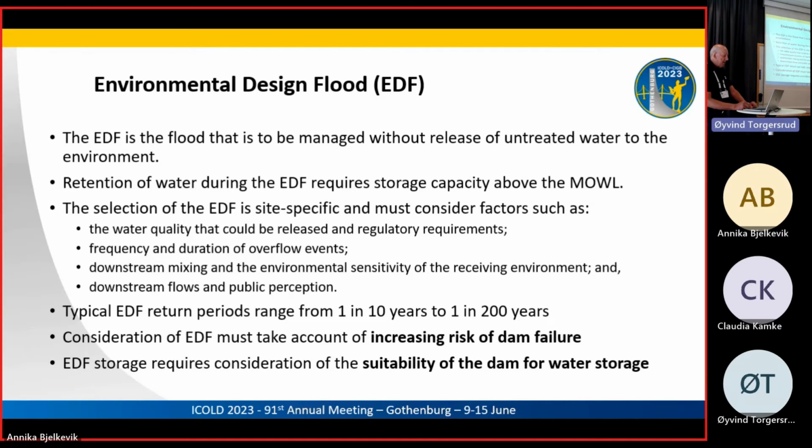And the more water we store on the dam, the more we're going to increase the risk of a failure through overtopping or piping, and there's other failure modes. And in some jurisdictions, like even in Australia, in one particular state, the regulations are that they determine the dam to be a no release dam.